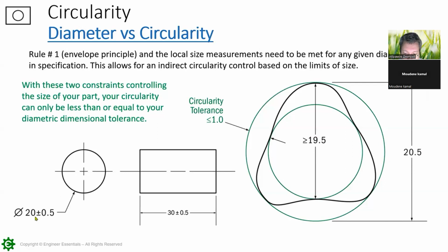And maybe you're putting a position tolerance on it. Well, remember that whenever we get into adding our geometric tolerances like position, if we give a sloppy tolerance to the diameter, position is not going to come back and help you as far as the scenario we're looking at right here, this lobing. That is from the form. That's going to be controlled by size.